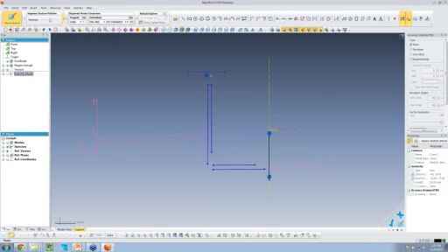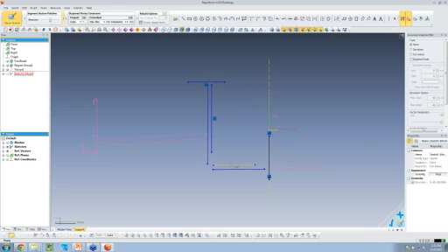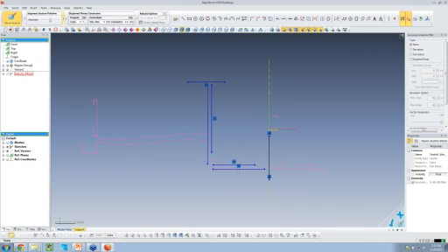And now it's going to take the opportunity to clean this up a little bit. So I have this line that is kind of freeform space, but look what it did. It automatically snapped as a horizontal. So now it's actually adding some parameters to that. If I'd like to add some more parameters, I can also float around a little bit, and I can add a vertical constraint to this, and add maybe a horizontal constraint to this, and add a horizontal constraint to this. So when I revolve this part, I know it's flat. It's going to be in a flat state.